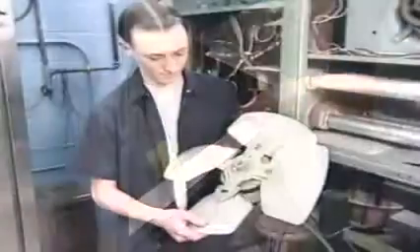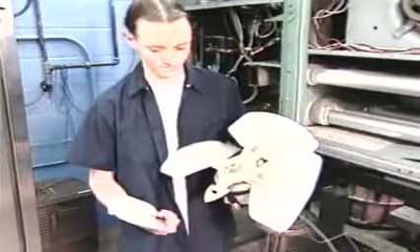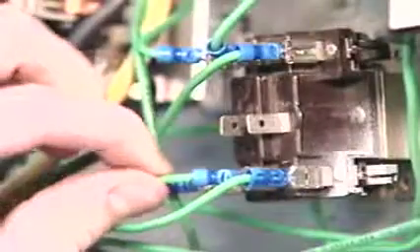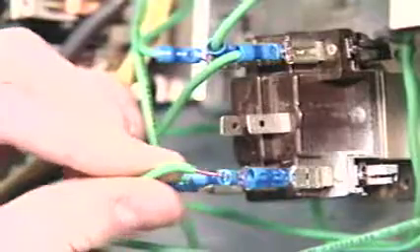The purpose is to look for obvious symptoms of the problem, such as a dirty filter, a filter that is missing altogether, a fan that doesn't operate or has damaged or missing blades, a belt that is broken, worn, or loose, broken or loose wires, dirty or corroded coils or fins, damaged piping, blocked supply or return ducts, or overheated or burnt wires and electrical connectors.